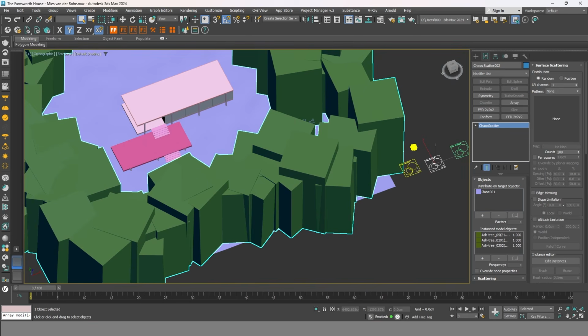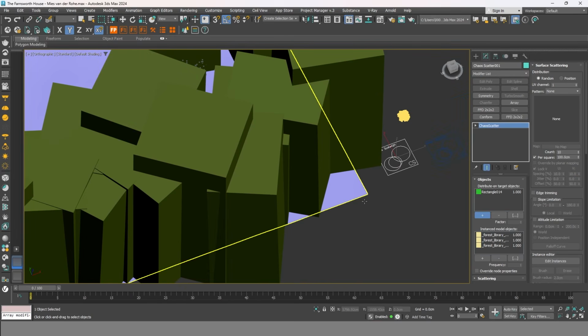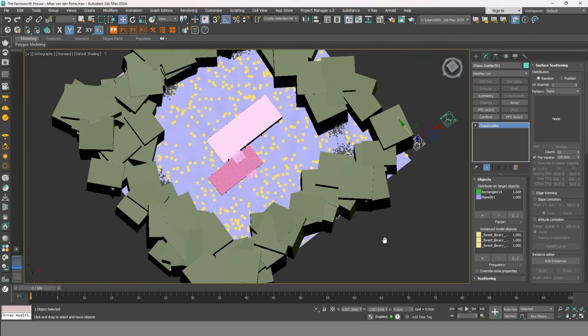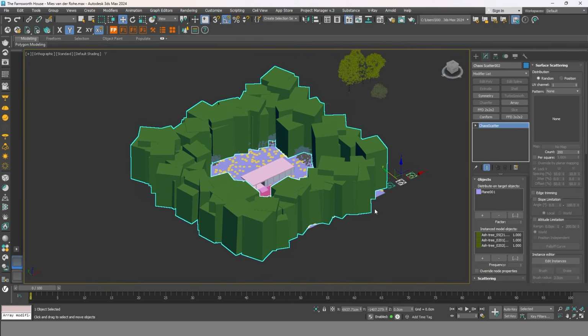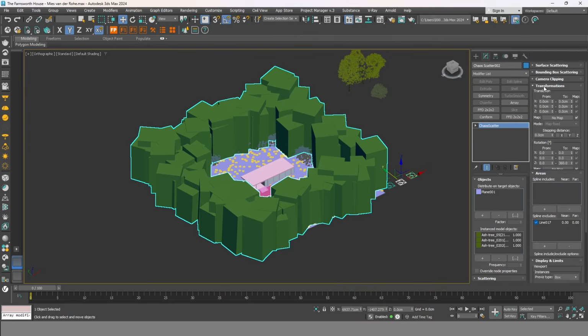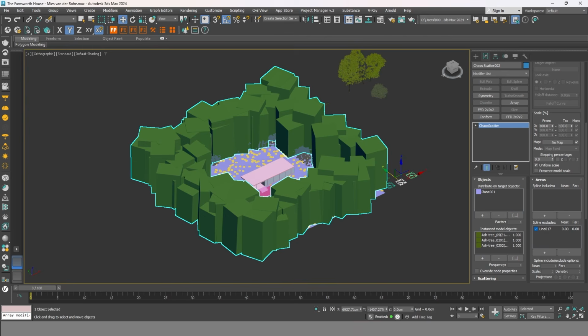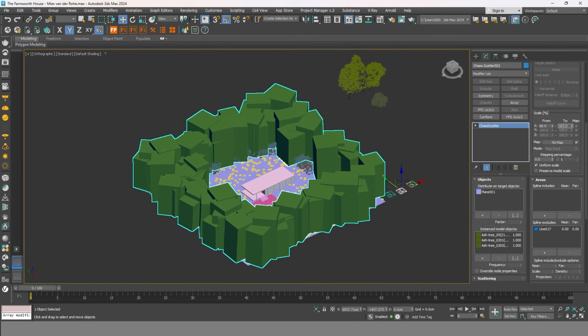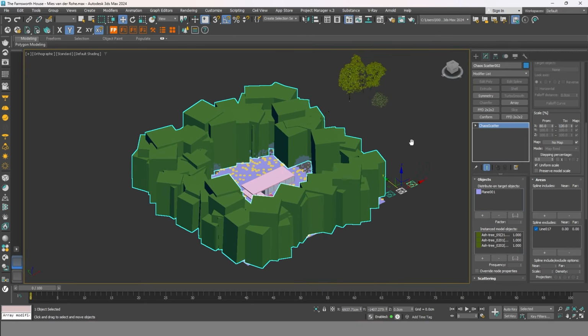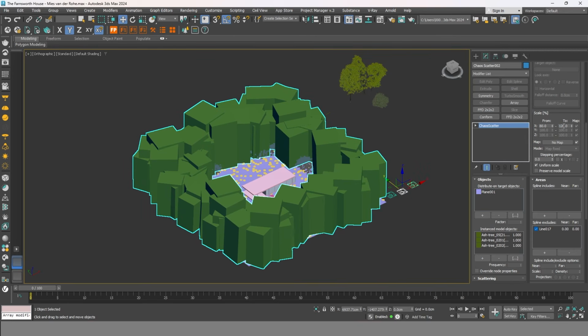That's good. And of course, we need to turn on the grass here. To make more variations on the trees that surround the building, you can come here, and in the transformation, reduce or add more variation on the scale of the trees, which gives us a more realistic view. So let's go ahead and make it 80% to 120%. Let's just type this, 70. Yes.